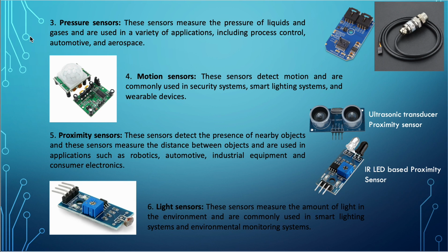It could be something like Coca-Cola, Pepsi, things like that, to measure the pressure inside those. From a small bottle to the large container, they mix the product in. Everything would be measured, and because we know the size of the container, we can even know how much liquid is inside the container through a pressure sensor. So that's another application. Not only checking the pressure for safety while the liquid is traveling, we can actually use that data to calculate the amount of liquid that is inside a container, right?